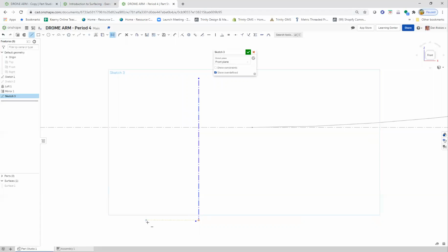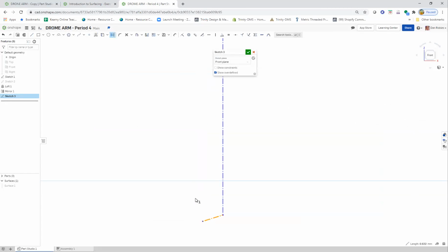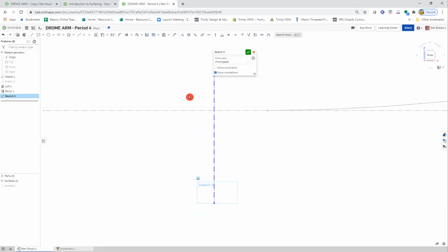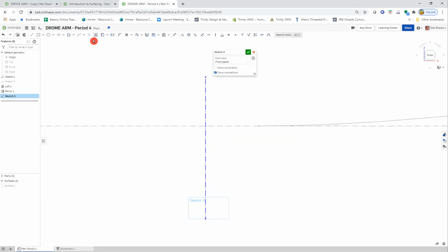Here's a horizontal construction line. Whoa, what's that? Oh, it's a little baby one. I didn't mean to draw that in there. Okay, so line for construction, click on the bottom of this, move it out sideways, make sure it's horizontal. Okay, another line for construction over here somewhere. Don't really care how long it is, as long as it's about that size.